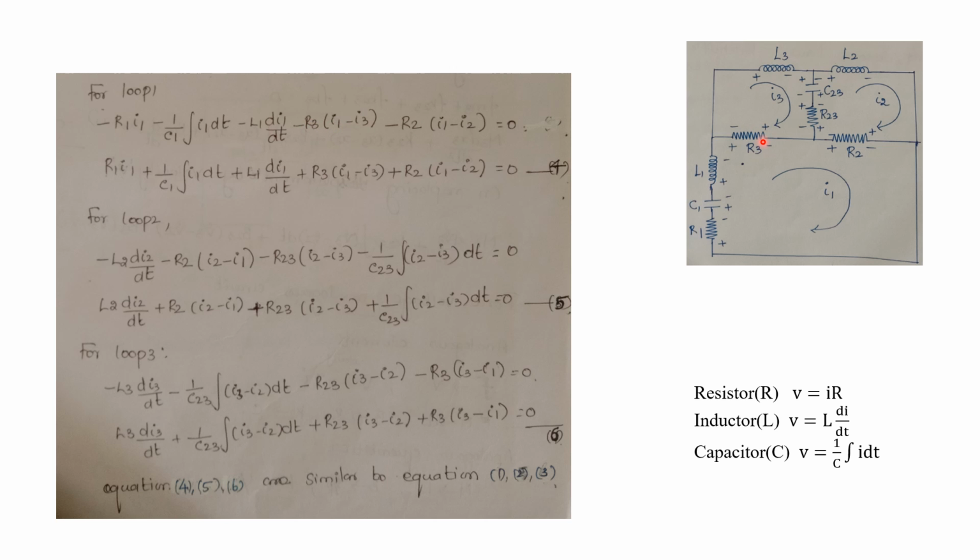Two currents are flowing, isn't it? So we have to write the difference in current, because both are flowing in the opposite direction. Understood? If both the currents are flowing in the same direction, we have to add the currents. If you are assuming the current direction as clockwise, then it will always flow in the opposite direction, and we write the difference in current. Now we are writing the equation for loop 1, so this I1 current should come first. Minus I2. That will be equal to 0.